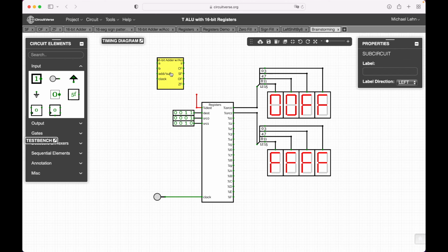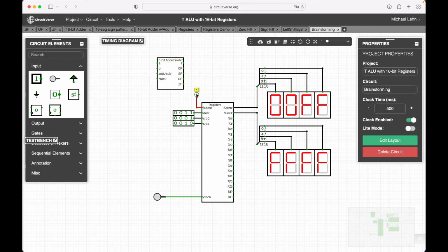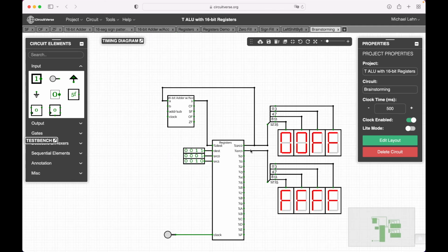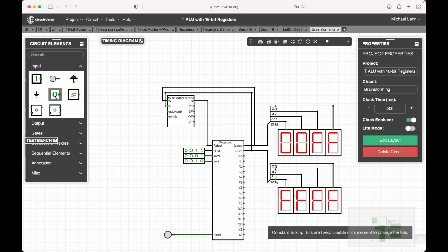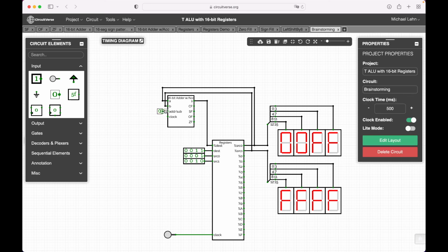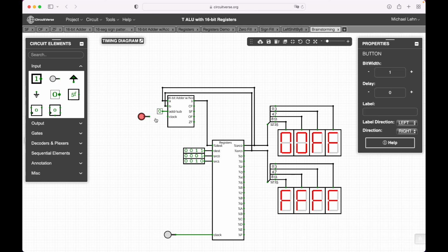And then the bit pattern that should be stored comes here from this S. The operands are this register source 0 and register source 1. Actually, we can discuss which should be operand A and which should be operand B, but here it actually doesn't matter. Now I want to use an addition, so I use here 0, and I also need a clock signal.